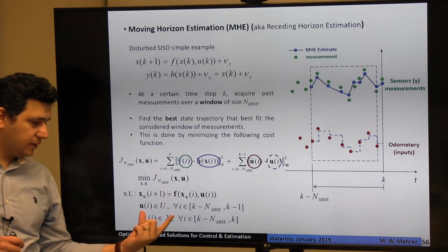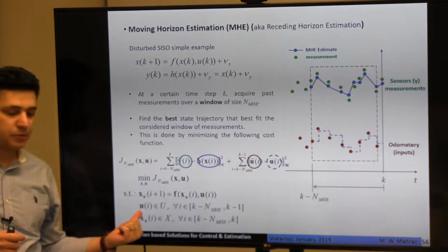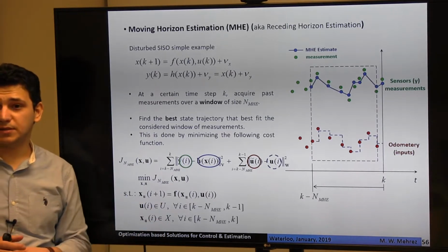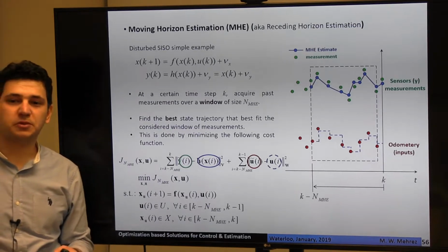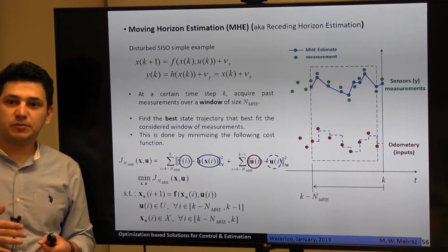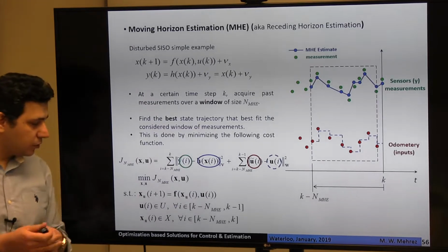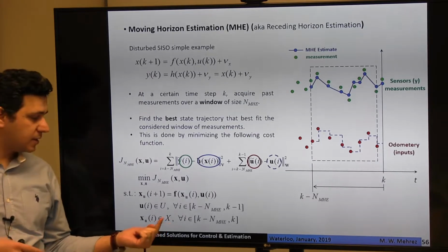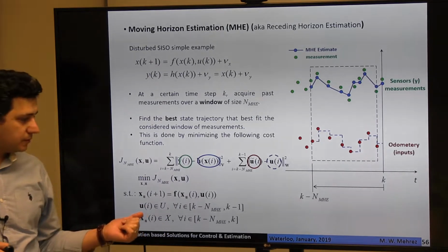Okay. And the nice thing about MHE is, if you already know the control margins for your control input and the state margins for your estimated state, you can put these as constraints. Say, for example, we have a robot that is inside this room and we're doing state estimation on it. We know that the robot is inside this room. So if the state estimator would like to give me different values for the state estimate, we will ignore the ones that are outside the room, right? And this can be translated as adding a constraint on the estimated state. The same for the control actions, right?